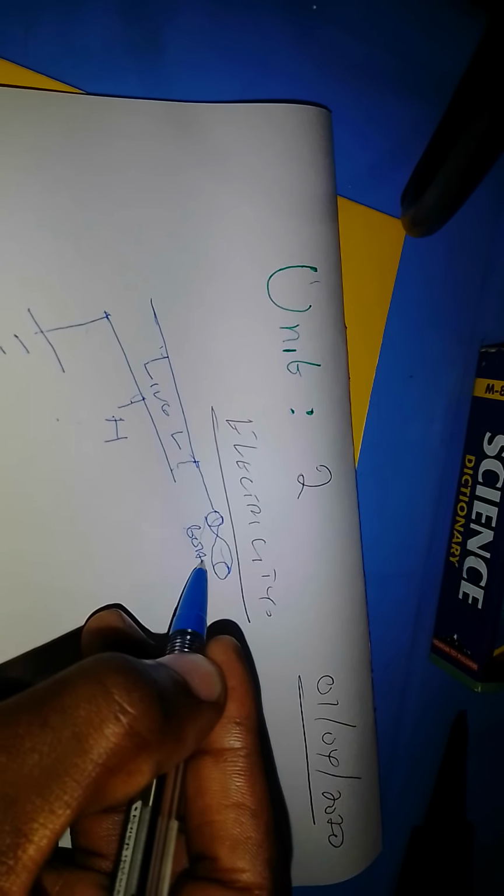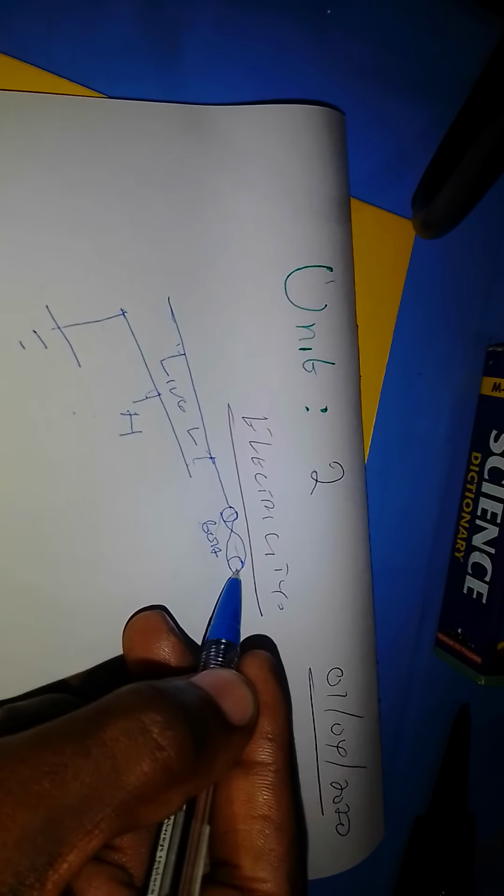We're going to see here shortly how this ring main circuit is connected. So how do we start with the ring main circuit? There we go. Now, of these two wires, the live wire has a fuse. We call this the company fuse. It is about 60 amperes. 60 means it only allows a current below 60 amperes to flow through it.